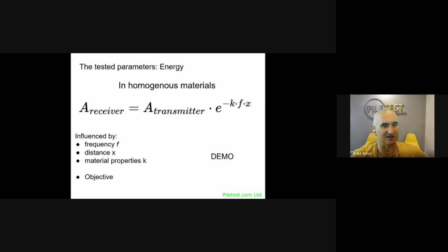And for the maximum distance, what governs that is the size of the defects that you want to see. Now, as a rule of thumb, you can only see defects which are about a third in size of the distance between the tubes. So if you have a 1 meter spacing between the tubes, you can see a defect which is about 30 centimeters, about the size of a basketball. If you have 2 meters, it's going to be already 60 centimeters, which is a very, very large defect.